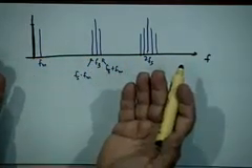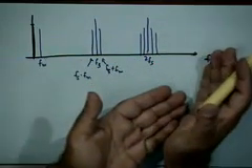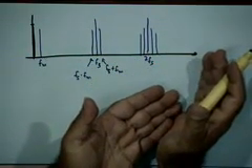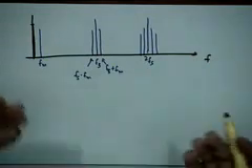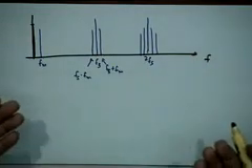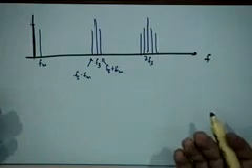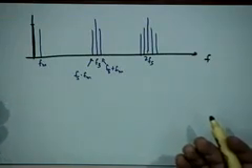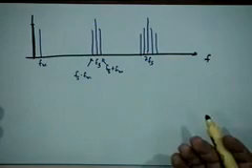Again, just put a low pass filter, because all these signals will simply disappear once again. All these components will still. So the demodulation for a PWM signal is therefore once again the same low pass filter that you are using for the case of PPM or sample signal.